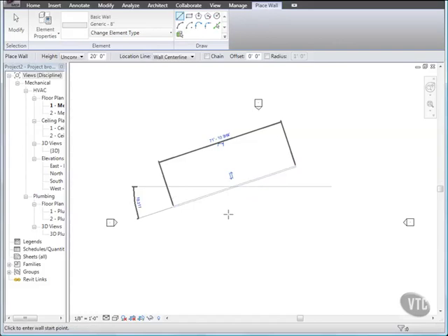Enter the 2 shortcut keys SM. This is a snap shortcut key that restricts all snapping to midpoints. Notice now that when you move the cursor along the wall, the cursor now snaps only to the midpoint of the wall. Click Modify,